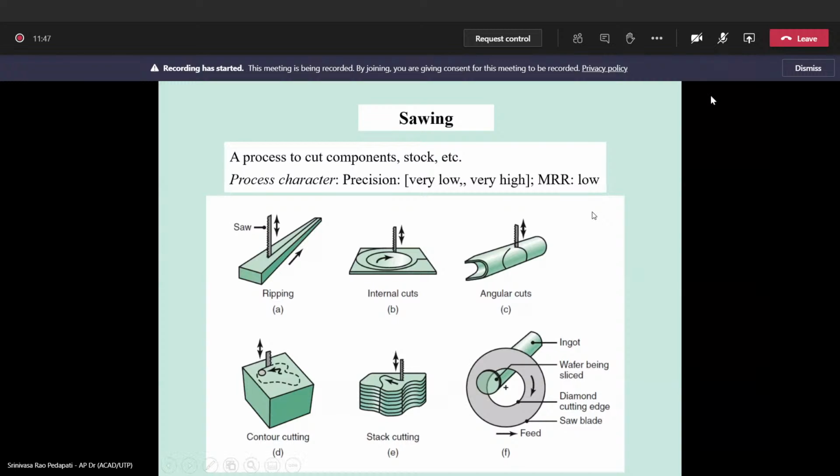we're going to discuss other operations. As I said, in the previous class we discussed the lathe and the operations that are possible with the lathe, like turning, taper turning, threading, making holes, drilling, boring, and so on. After that, we have seen another kind of machine tools like planer and shaper, which are fundamentally used for shaping plane surfaces or making plane machining. So that means shaper and planer.